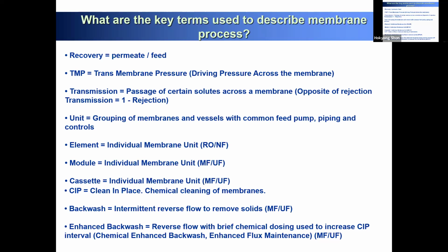So for recovery in your assignment, in general, for seawater, we design 40 to 45%. If you go for more than 50%, you will have a lot of inorganic scaling in the membrane element. So 40 to 45% recovery, you can design for your seawater desalination.